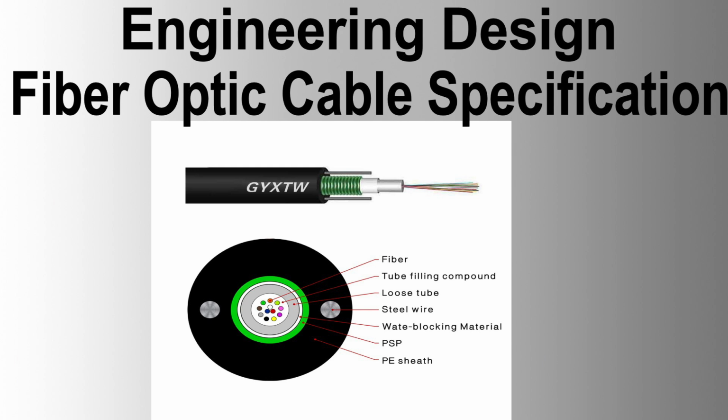Fiber geometry and performance requirements for G.655 single-mode fiber. Fiber type, G.655 compliant single-mode fiber, 9/125 µm. Mode field diameter at 1550 nanometers, 8.4 ± 0.6 µm. Clad concentricity error, 2.5 µm. Cladding diameter, 125 ± 1 µm. Cladding circularity error, 1%. Coating diameter, 245 ± 10 µm. Proof test level, 0.7 GPa, 100 kpsi. These requirements ensure that the fiber optic cables meet the necessary mechanical, optical, and environmental performance standards for reliable operation in the specified conditions.